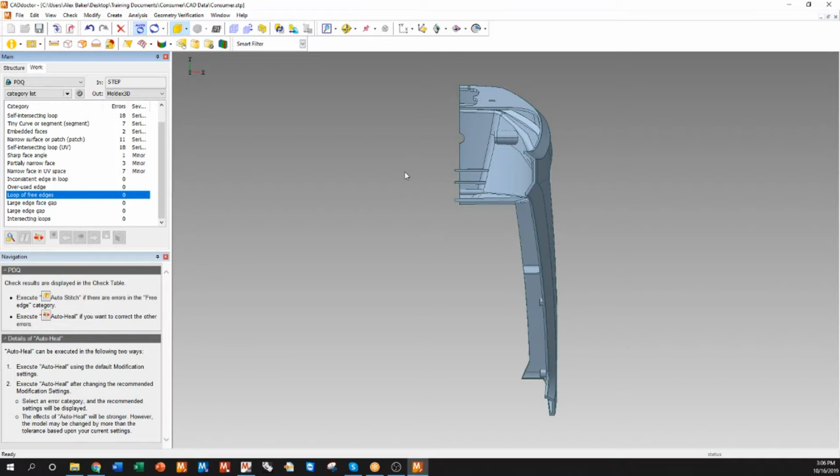The latter condition is more common and occurs because of a translational error between your CAD system and Moldex3D. It's not uncommon for this error to show up, and the Auto Stitch tool allows us to merge those surfaces back together as they initially were intended to be. So the Auto Stitch tool will use a tolerance to merge 2 edges back together, or 2 surfaces back together.